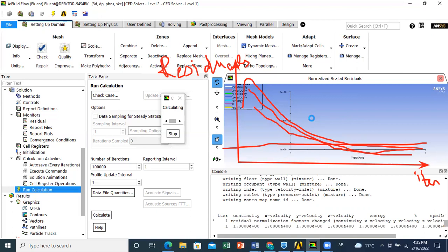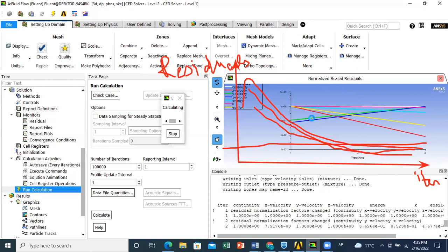So let's say you can explore at certain locations what the temperature is for mesh 1, what the temperature and velocity are at this location, etc., for mesh 2. So you take several grids and you see how your predictions are varying. When you see that for 2 consecutive meshes the difference is not very high, you can say it's fine. No need to increase the number of elements anymore, because if I'm increasing the number of elements, I'm not getting more accurate results.